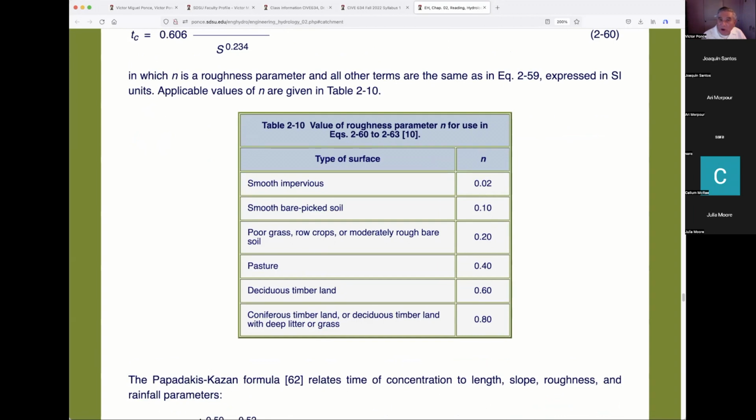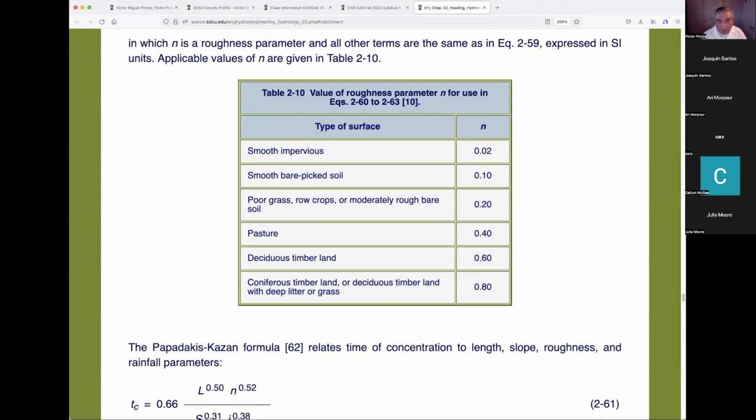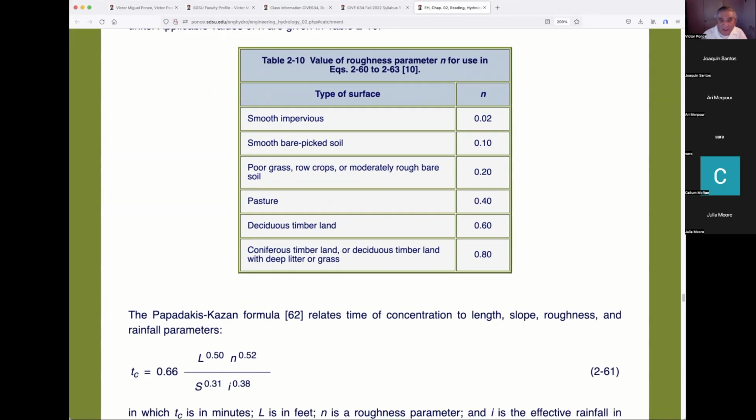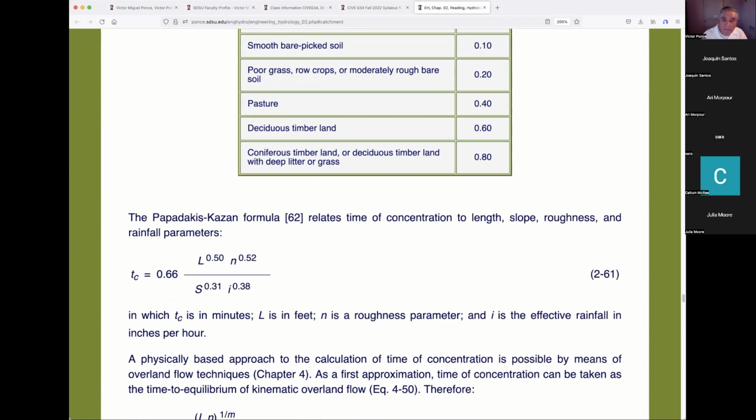And they went back to the drawing board, and the next day they came back and they said, we're standing by our number. We believe that in the Everglades, the n value that we're going to use, the frictional value for laminar flow conditions, should be 1. So they're beyond what I wrote in my book. I never actually considered changing this table because this is a table that was developed by the Army Corps of Engineers based on many, many projects. The Florida project and the Everglades, I believe there's only one Everglades or similar type wetland as large in the United States. So I didn't think it was necessary that I should change the formula.